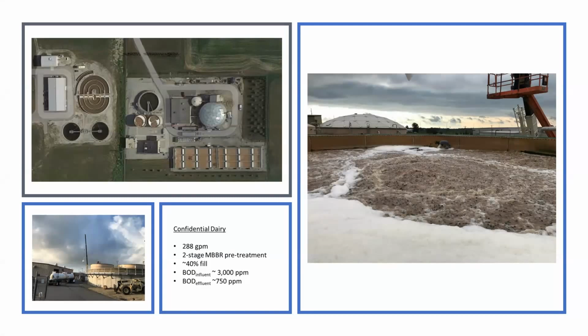What I did not point out is that when whey processing is present, whey can contain COD values well in excess of 10,000 ppm COD. So for this particular plant, this client would have fluctuations based on whey in the system on a weekly basis. It was enough for them to consider treating the whey separately.